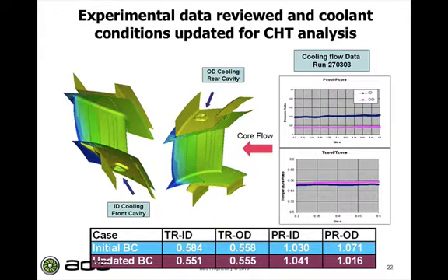So what we found was, the assumption we had made was that there was, again, relatively small variation between what was coming into the inlet of the annulus and what the vane was actually seeing. But when we looked into the data in detail, we found that actually there was a significant amount of variation around the annulus for these coolant supply pressures and temperatures.